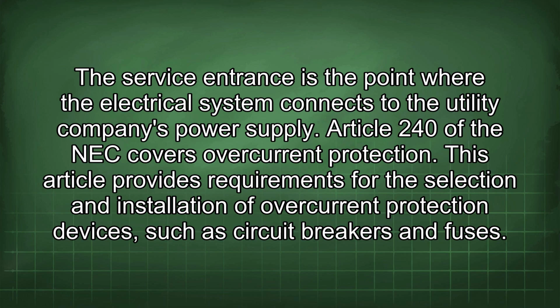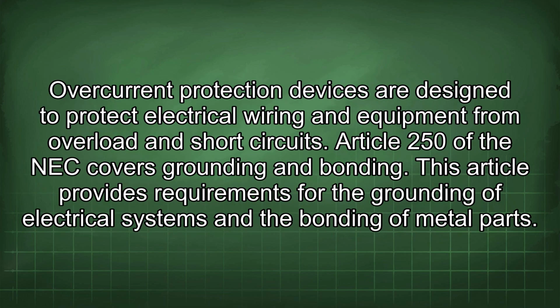Article 240 of the NEC covers overcurrent protection. This article provides requirements for the selection and installation of overcurrent protection devices such as circuit breakers and fuses. Overcurrent protection devices are designed to protect electrical wiring and equipment from overload and short circuits.